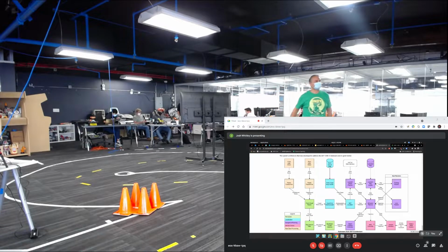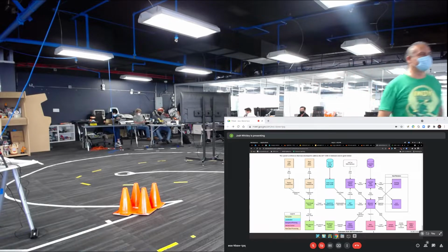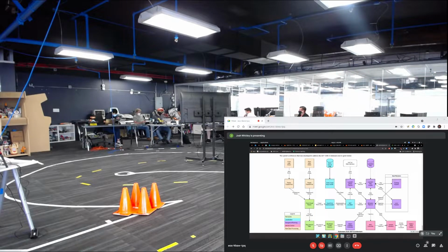The MPC controller, this part is actually wrong. The MPC controller then sends a set of commands, not a trajectory, to the vehicle interface. And the behavior planner actually chooses what gear the vehicle should be in, so it passes that to the vehicle interface as well. Those get turned into vehicle-specific commands for the drive-by-wire system or software that we're using on the car and get passed down to the car. So that is the entirety of what we use during the autonomous valet parking demonstration to be able to park in a spot and then return from the spot.